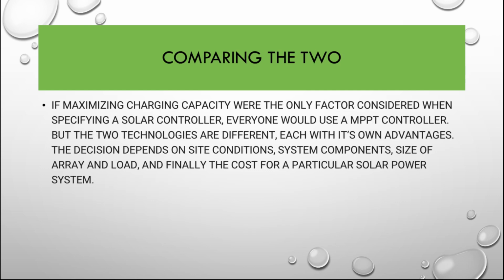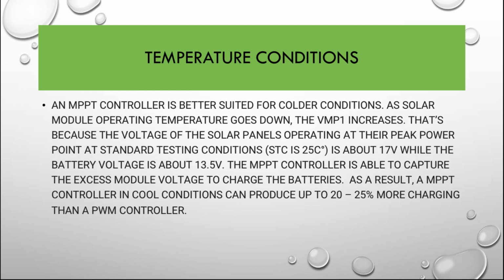Comparison of MPPT and PWM. If maximizing charging capacity were the only factor considered when specifying a solar controller, everyone would use an MPPT controller. But the two technologies are different, each with its own advantages. The decision depends on site conditions, system components, size of array and load, and finally the cost for a particular solar power system.